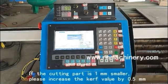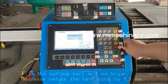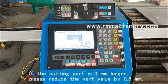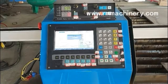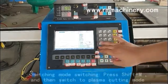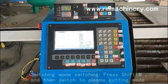If the cutting part is 1 mm smaller, please increase the curve value by 0.5 mm. If the cutting part is 1 mm larger, please reduce the curve value by 0.5 mm. For mode switching, press Shift M, and then switch to plasma cutting mode.